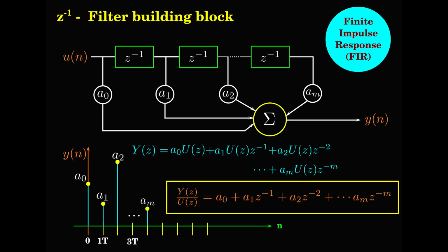You can use the difference of two values for detecting the slope of a time signal. So the discretized time signal, if you want to find the slope of that, you could use a difference filter. So that is also a FIR filter.